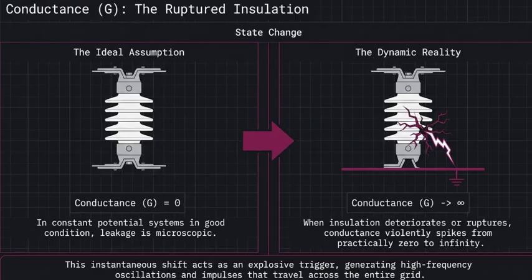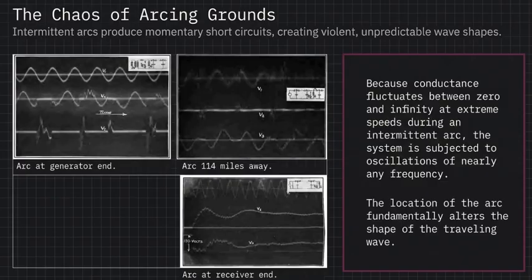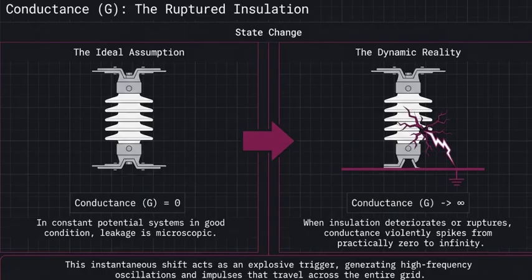Right. Let's look at conductance first. When engineers calculate power transmission lines, they usually treat conductance as practically zero. Because of the insulation. Exactly. The insulation, whether that is thick rubber shielding or just the empty air between the wires, is doing its job.